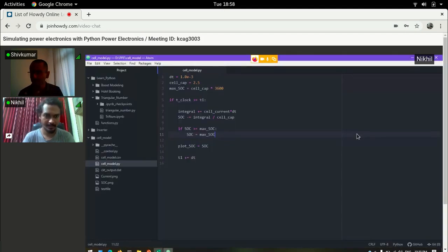Now, you've already learned pandas and everything else, so you can read that Excel file and use some Google. Again, you will probably be in SciPy or NumPy. Yeah, we can use dictionaries for that, right? Exactly. So basically, you must find out where the SOC lies, interpolate it between two values, and find out what will be the voltage corresponding to that SOC. And then when you find the voltage, that voltage will be your output of the control file.